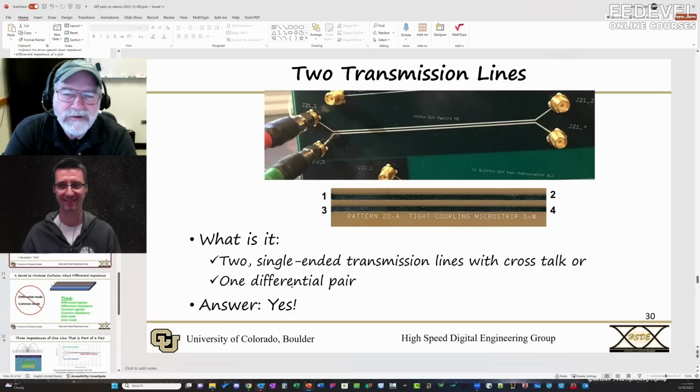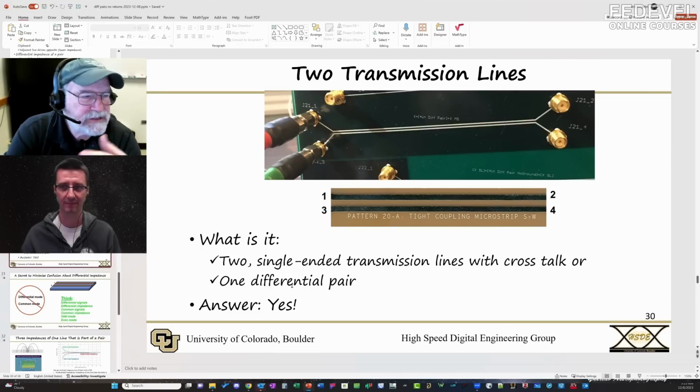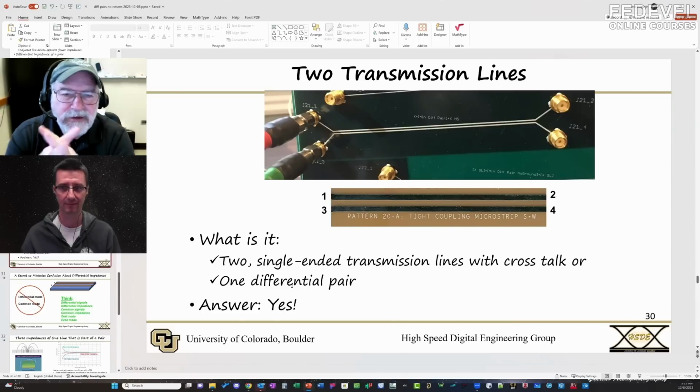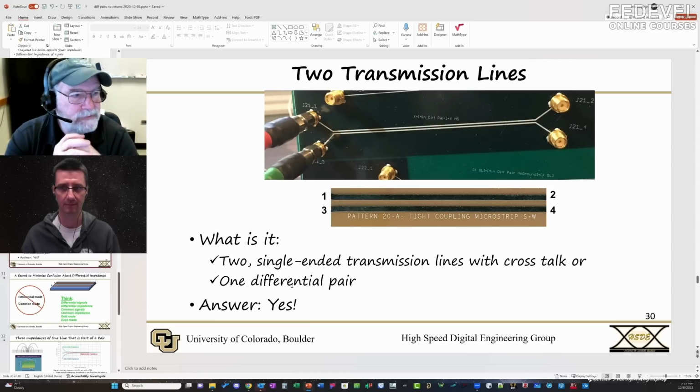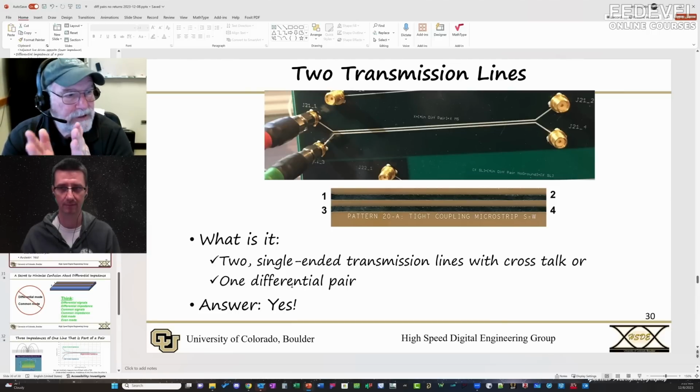Well, unfortunately, that's another one of those it-depends kinds of answers. You use transformers for a lot of different things, but when it comes to signal path, it's typically two kinds of things. One is as a balun, and a balun is a component that will convert a single-ended signal into a differential signal, or vice versa. So that's one application. The other application is isolation. Actually, three applications, I guess. Isolation of the signal, and the third is filtering.